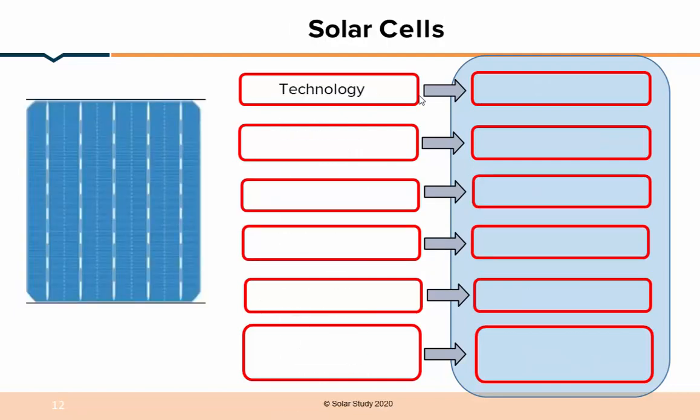We already discussed so many times how solar cells are fabricated, but still, because we are manufacturing the module, we have to know about the solar cell basics. So, what is the technology? Either it will be a monocrystalline, multicrystalline, amorphous, or PERC solar cell. These are the technologies. Then efficiency. How much efficiency should be there? It should be 17 to 22%. Then bus bars: 4 to 5.